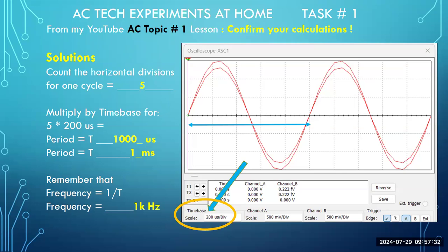All right, so one cycle is defined as the part of the waveform where it begins, and typically we look at where it begins from the 0 volts DC reference line, which is this dark horizontal line across the middle of your oscilloscope screen, where the waveform begins, and then it rotates, meaning it moves. It's rotating up to some positive peak, and then rotates back down over the side, decreasing down to 0. Once it hits the 0, that's not the end of one cycle. It then moves in a negative direction below the 0 volts DC reference line to some negative peak.